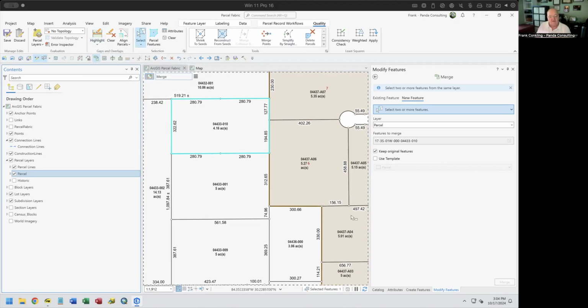And you'll see there is nothing in here that goes and does it. This takes the place of running topology against your data just to look to see whether you have gaps or overlaps. Now, with the merge maintenance, this is kind of useless. You really don't need that, but I just want to get you into that routine that should be a step that you always do after you do any of these maintenance routines.